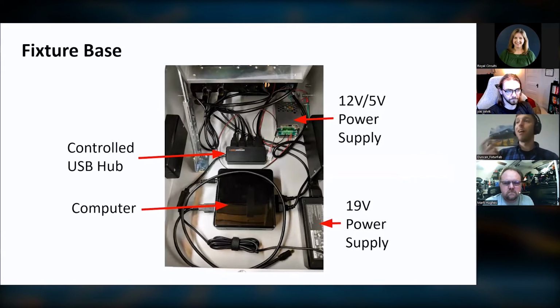And then if you have a device fail that, you're like, okay, we don't have 5 volts on that voltage regulator. So we can't really point to exactly what component is wrong, but part of the debug guide that will go along with that system is like, okay, test case 1.2 failed. That tests the 5-volt regulator circuit. So go look at U2, which is the 5-volt regulator IC or something like that.